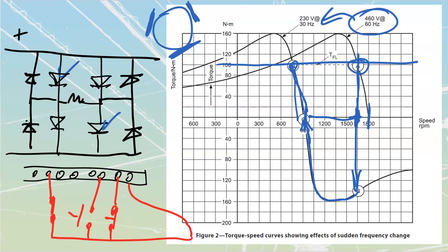As far as protection on our motor, once again, we need a motor that has a high insulation class rating. Usually we want to see an insulation class, as far as temperature, pushing up towards the H level. We also want to make sure these are rated for inverter duty, which means they're going to have oversized windings, magnetically braced, etc. Those windings do have to be capable of withstanding those high voltage spikes. That's that reflected wave that we talked about before as well.